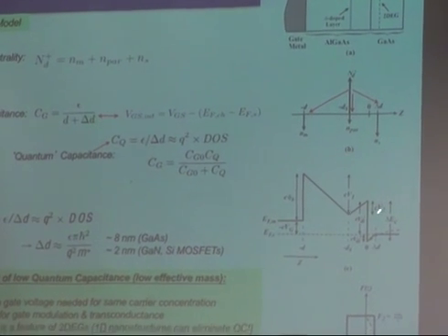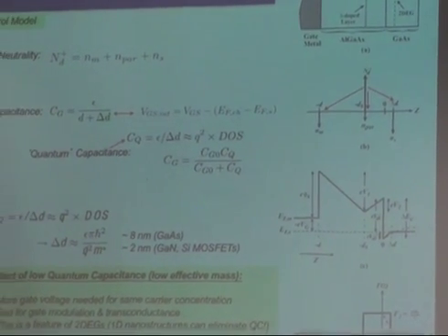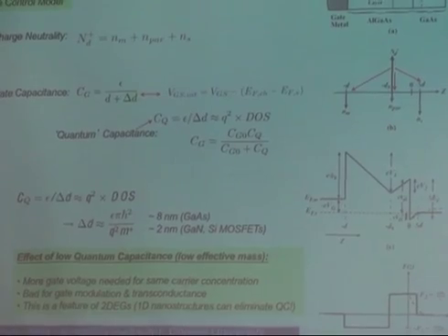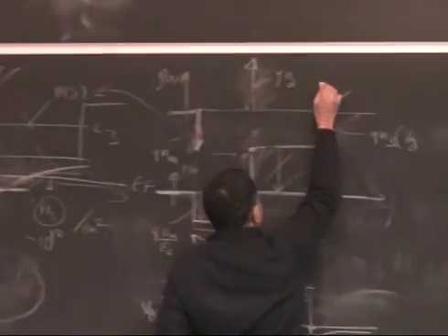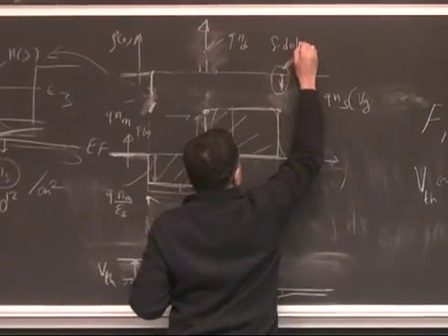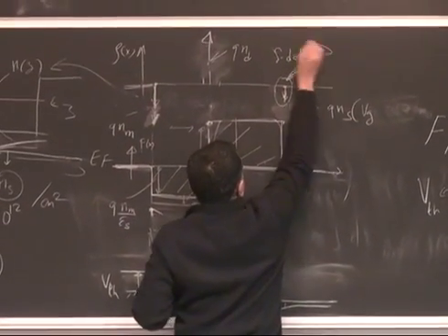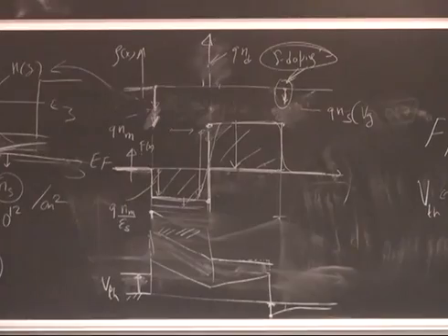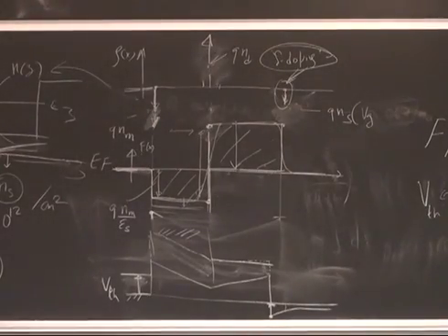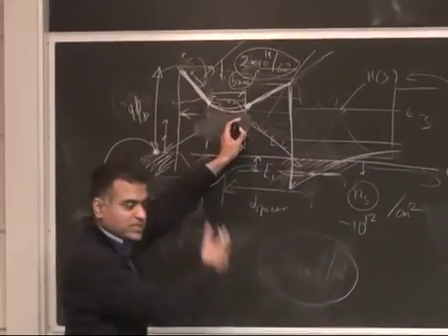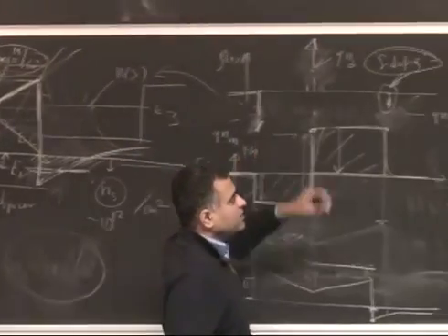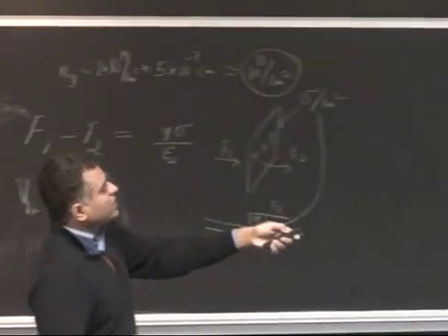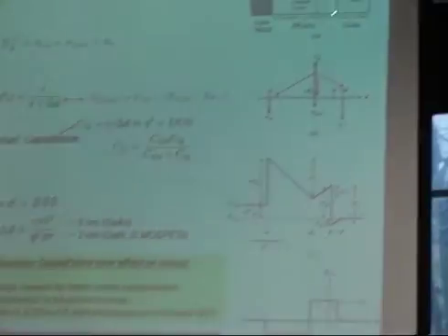So you have a delta doping sheet here. By the way, if I shrink this dopant layer down to a very narrow region, that's what's called delta doping. It's just the name that has been used. If you shrink it down to a sheet, with the dopants only sitting in a sheet, it's called a delta doping. So this is your delta doped layer, gate metal, barrier layer.